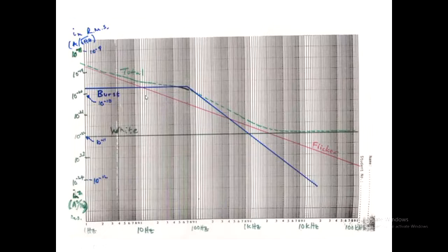And the usefulness of the log plot graph here is that you can make quick changes between amps per square root of hertz and amps squared per hertz. I've done a rough indication of changing from amps squared per hertz to amps per root of hertz in blue, the other one in black.